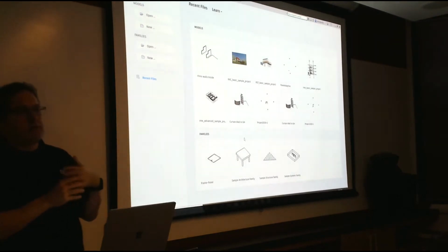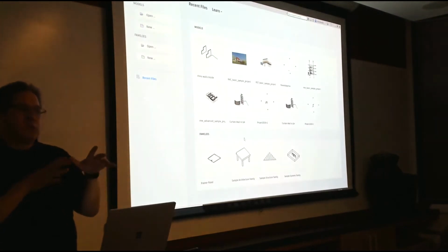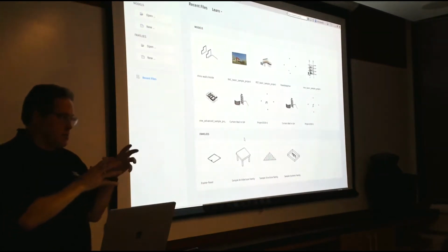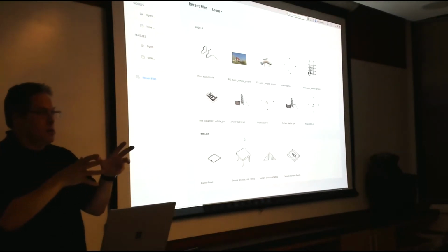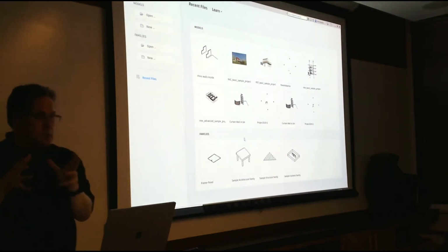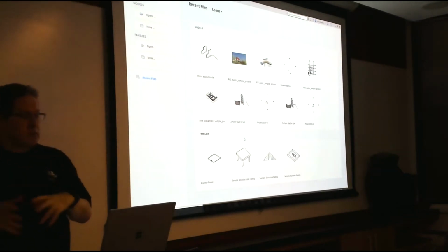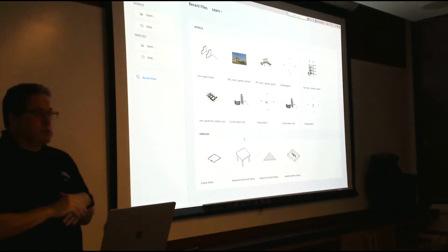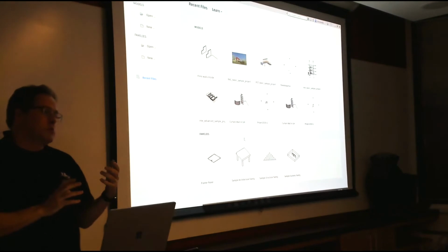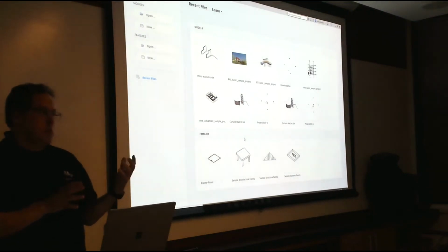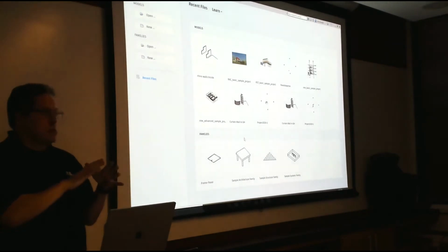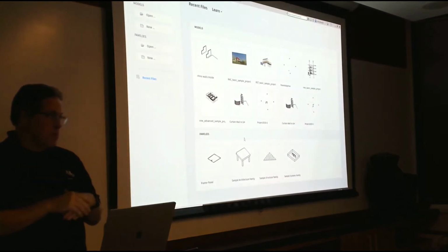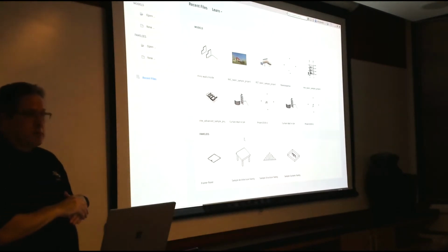Alongside that, we've added a very powerful quad mesher. So you can take a scan or a mesh and you can convert it to quads. Quads, oddly enough, convert to SubDs really well. SubDs can convert to NURBS. So now you have kind of a reverse engineering way of going. Another thing for architecture and engineering that's interesting is that quad meshers tend to find principal curvature really well on complex shapes. So you can use it to map out a form and then use it to walk across the form and create structural components if you want. So that's the quad mesher.